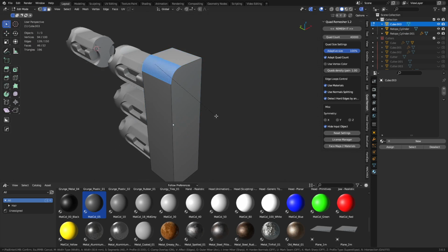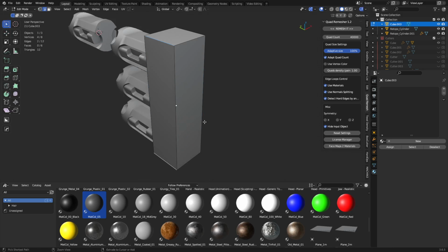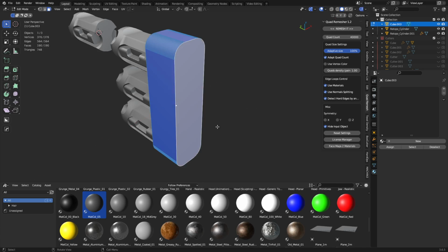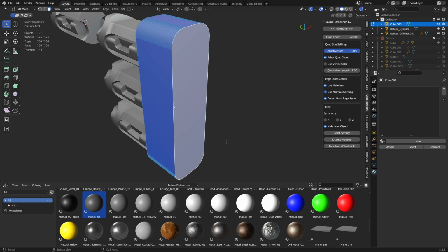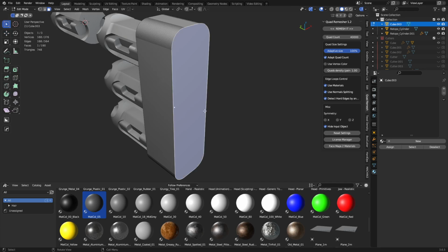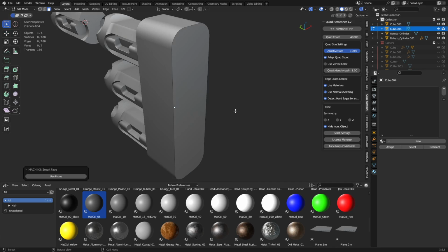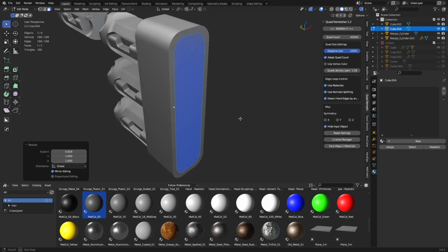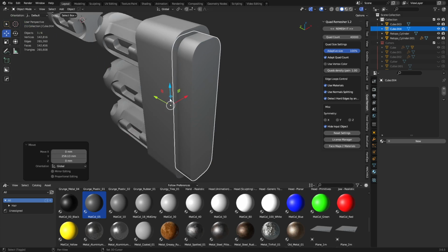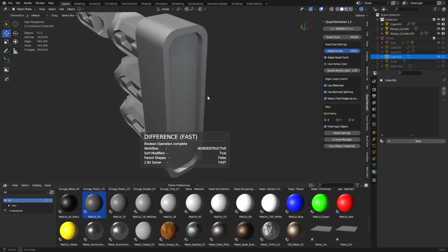We do a big bevel here or a big chamfer, whatever we want. Symmetrize it. We can do some basic modeling on it if we really wanted to. But I think it's kind of redundant to do that when you could just do, like, say, with machine tools, you can just separate a face using Smart Face, or you Shift D, duplicate P, separate selection, all that fun stuff. But we could take this new shape here, basically, we just created, extrude it, push it back in, we do a Boolean subtraction, boom, just like that.